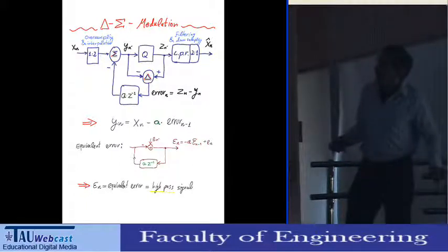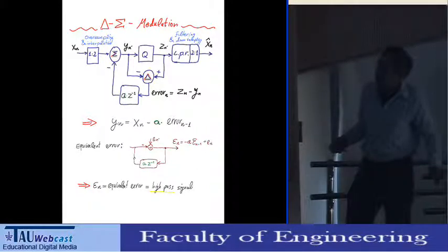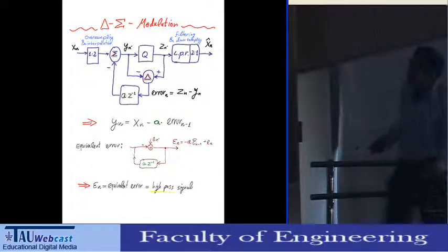I'm quantizing the source, but what I'm doing, I'm taking the difference, the delta between the input and the output of the quantizer. This is the quantization error. And I'm taking this error basically as it is, or maybe multiplied by some positive constant which is smaller than 1, and I'm subtracting it from the input in order to get the next sample to quantize. So this is the recursion that we are assuming here.